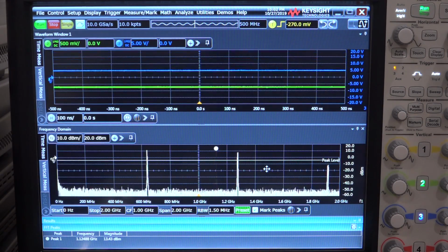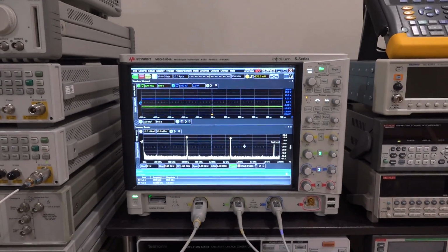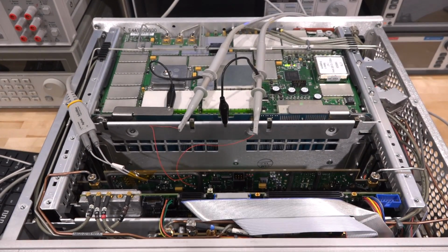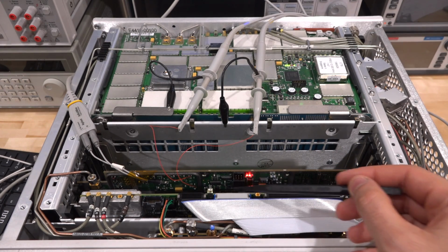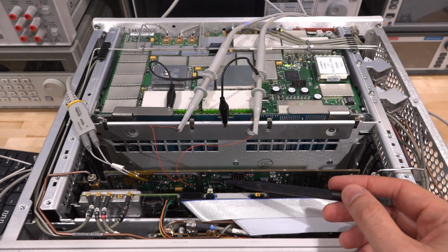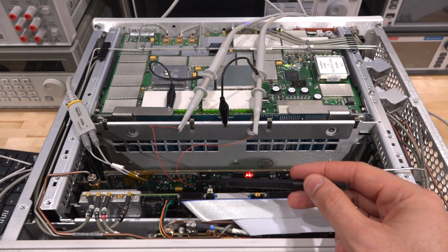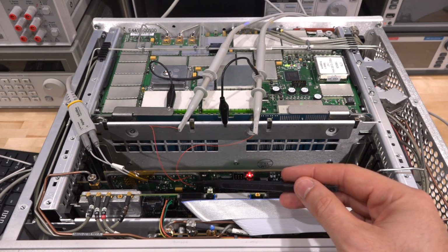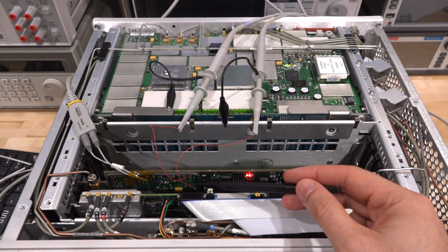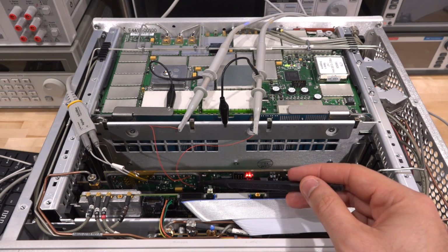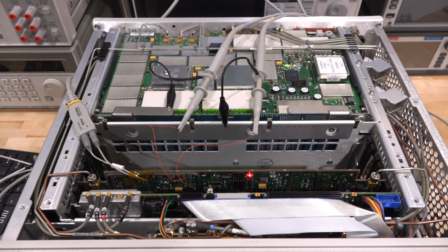So I'm beginning to think maybe there's something wrong with the varactors on the VCO, and the tuning curves are just all off, because it has to do some alignment and extract some information at the beginning, and maybe it's just not very good. Unfortunately, the alternative is that there's something wrong in this complex network that I showed you earlier. We can explore that as well, but I think I'm going to go ahead and change the varactors on the VCO and even the VCO transistor itself, just to make sure that it's not the varactor, because if the varactors are bad, even if one of them is bad, then we have a totally different tuning slope of the VCO, and that could cause part of the problem. So let's go ahead and try that.